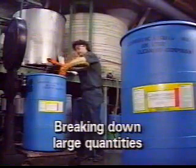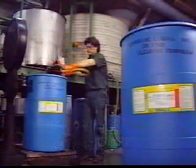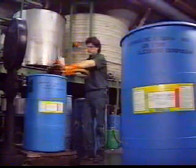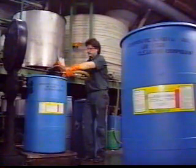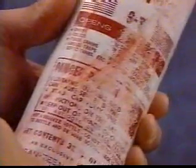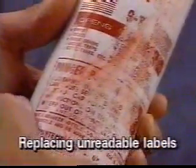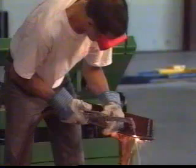Another reason for relabeling is to break down a large quantity of a chemical preparation into several smaller containers for distribution throughout the company. In this case, each of the smaller containers must be labeled. Labels may not last forever. If they become dirty, unreadable, or fall off, the employer is responsible for applying new ones. Labeling of hazardous chemicals is a requirement of the standard. There are only a few exceptions.